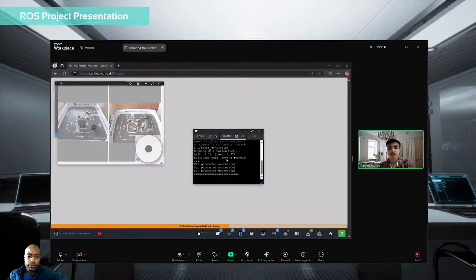So first it will find the positions, which means it will detect the wall and maintain a particular distance, and it will follow the wall. So you can see, first it has detected the distance left and front, and then it is setting parameters. Parameters are the velocity components, meaning linear and angular velocity, and then it will run in an infinite loop for continuous real-time operation.